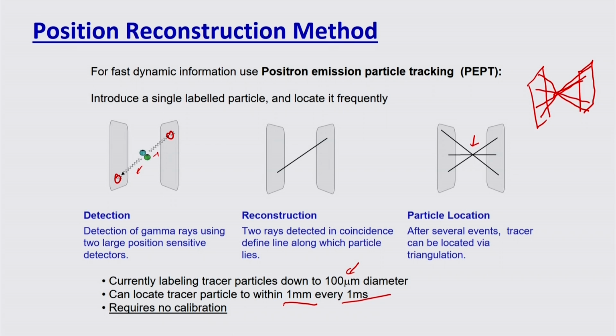Definitely these spatial and temporal resolutions are lower compared to PIV and LDA experiments, but the major advantage is that it can measure the flow in an opaque system, a very dense system, or where the discrete phase fraction is very high. That is the major advantage.